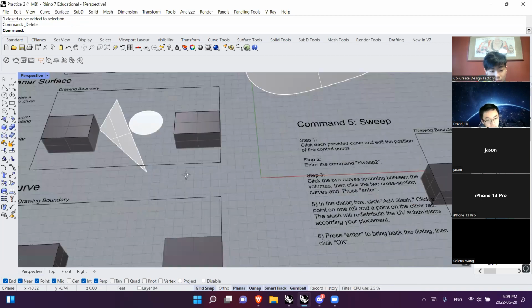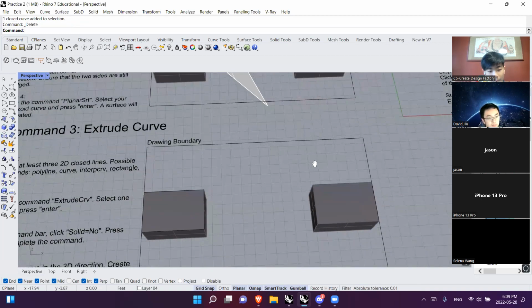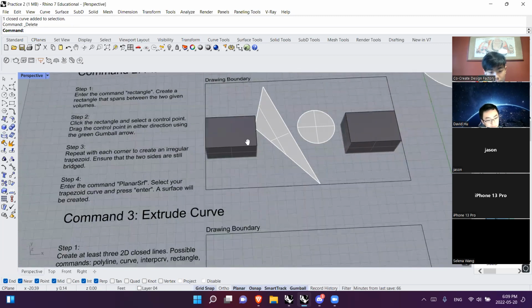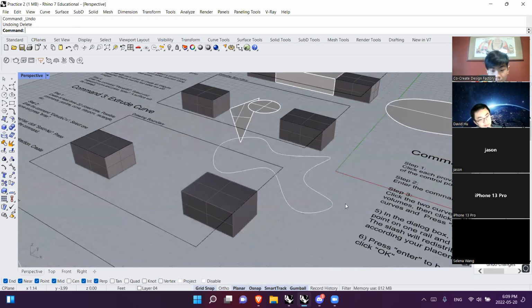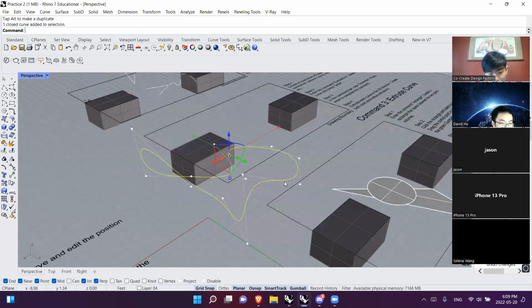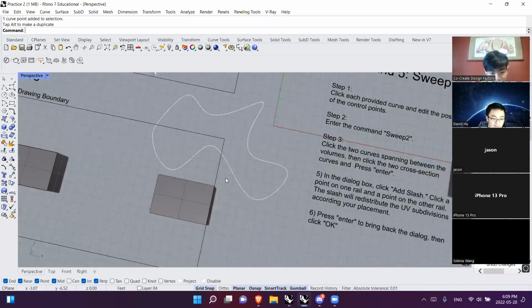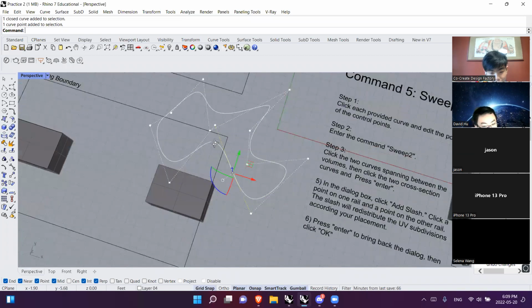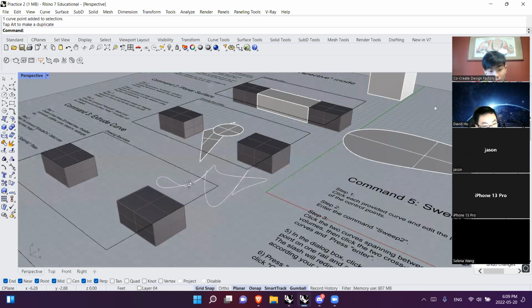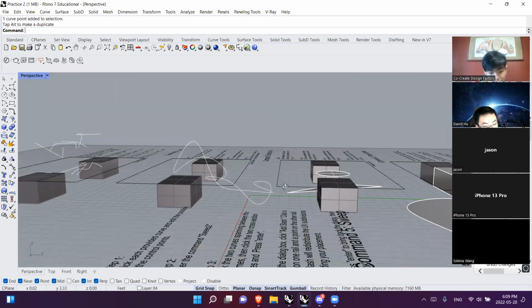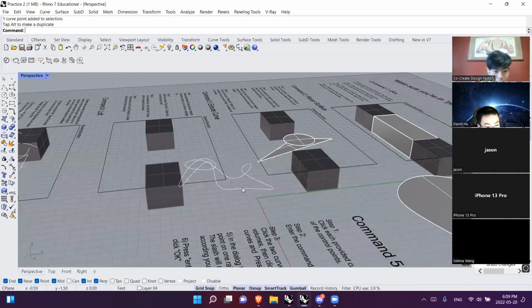Oh, you can also extrude 3D curves. Let's go back to this. So remember how to make a 3D curve. Click your control points, move them up and down like that. And you're welcome to try on your own. This is just me playing around with your curves. So here, it's up here. So now we have a 3D curve. A squiggly line, except it's in 3D mode.